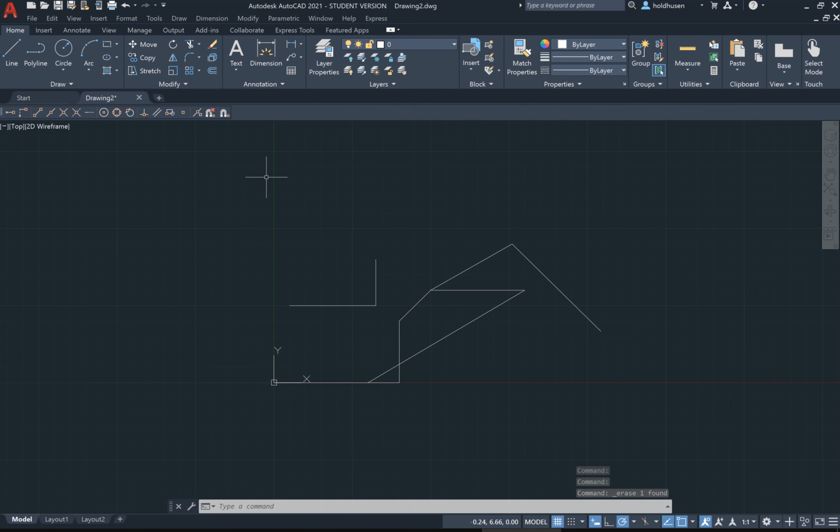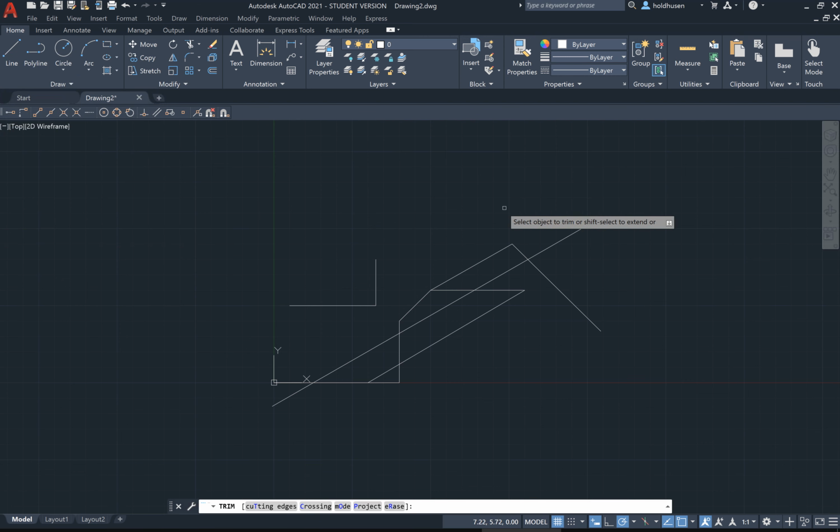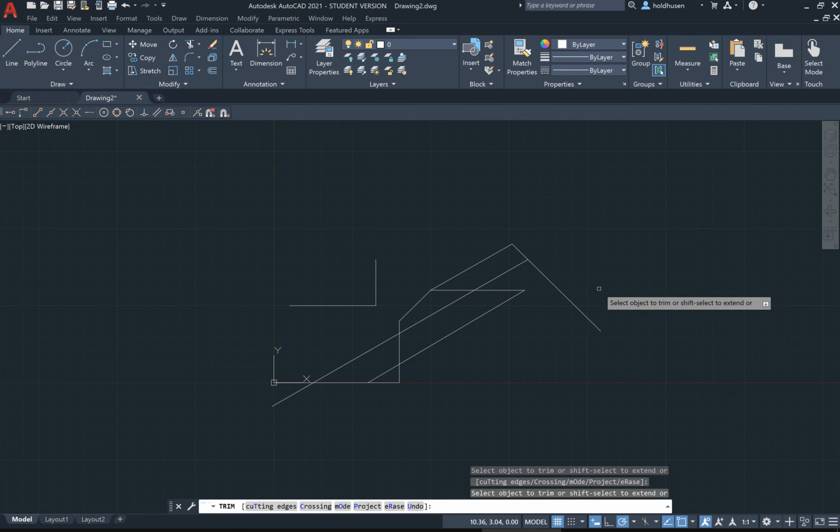One thing that you'll probably use an awful lot is the trim command. Let me draw a line in here like this, just some random line. Now, trim is when you just want to cut off a little piece of the line. Again, this isn't shown until chapter 2, but that is this little scissors here. So you can click on that, and what it'll do is just trim off the edge of a line if you want, or in the middle, just a section of the line. So that's pretty straightforward. Again, you can just click on it and then click on the section you want to erase.